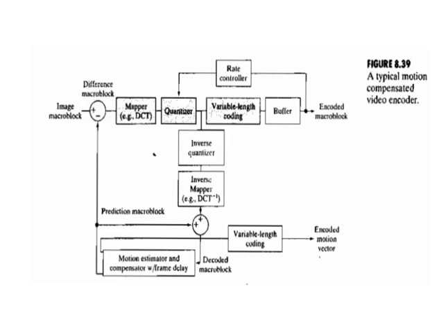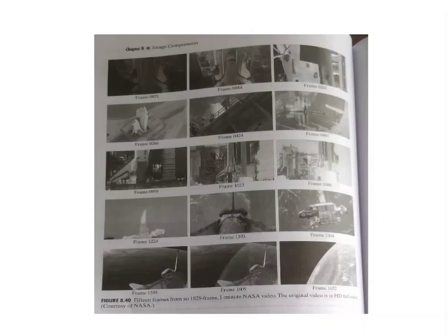To accomplish this, the quantization parameters are adjusted by the rate controller as a function of the occupancy of an output buffer. As the buffer becomes fuller, the quantization is made coarser so that fewer bits stream into the buffer. Let us consider a video compression example.